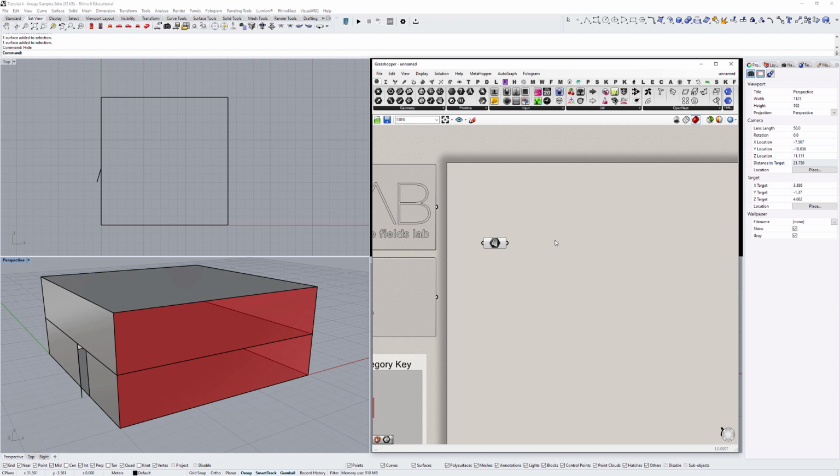Similar to the attractors from the previous exercise, we now need to generate a series of points that we can use. In the previous exercise, if you can recall, we set up a rectangular grid, and then we used that grid to generate center points. In this exercise, what we're going to use instead is divide surface. If you hover your cursor over it, you can see that it allows you to generate a grid of points on the surface. Let's put our surface into S, and by default we have 10 and 10. And you can see we've got 10 rows of 10 columns.